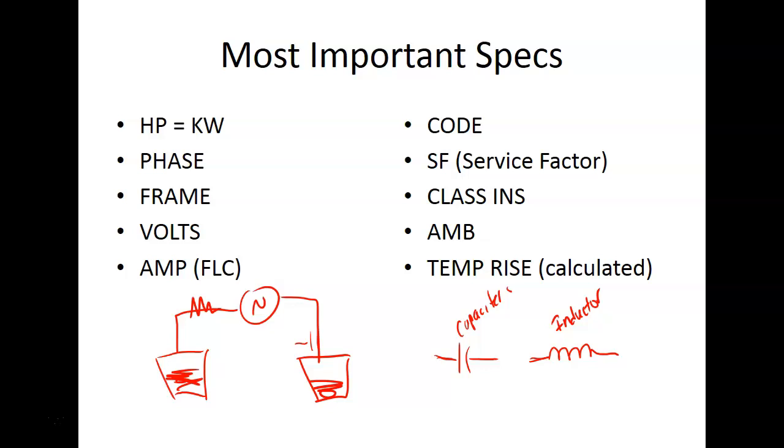Capacitors create a leading power factor. So if we get the right combination, they cancel each other out as far as apparent power goes.